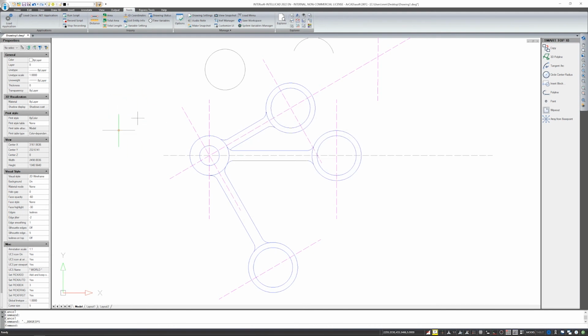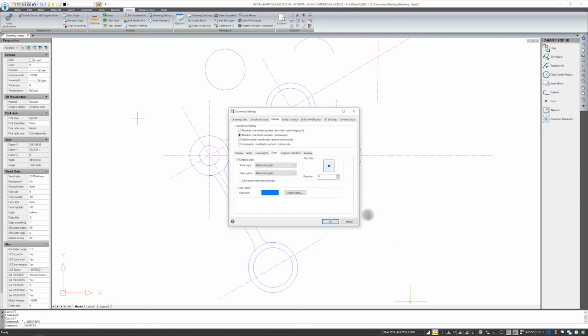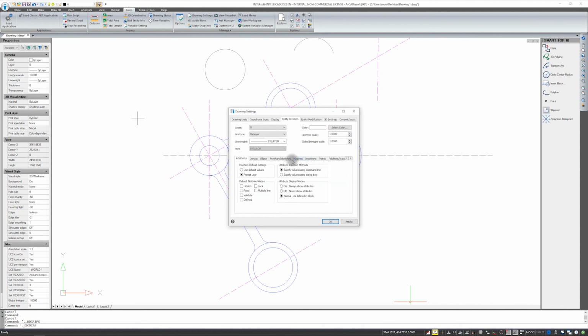I'll now click on OK to show you what it will look like, but I would like to come back to this window for a moment. This window will also appear if you entered the settings here on the status bar, in the grid settings, or I was here in this window for a while when the angles were set for the tracking options. So these settings can define both the elements when drawing, just like right here with the points. They can show what they look like. With ellipses, if you will enter the ellipses as ellipses or as polylines. Just remember that this change will only take effect when this option is checked.